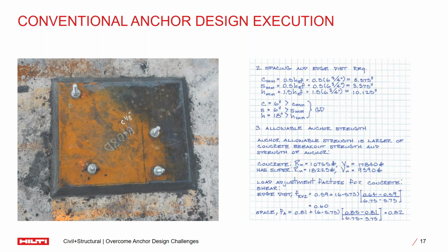Well, to see something this extreme is relatively rare, but we do encounter quite a bit where we have an irregular anchor layout pattern that we really have to respond to, especially when the contractor starts drilling in the field. They may do all the scanning. They'll find there's rebars within locations where anchors are supposed to be located, and we'll have to make adjustments on the fly, more or less, to make the construction work and keep the project moving forward.